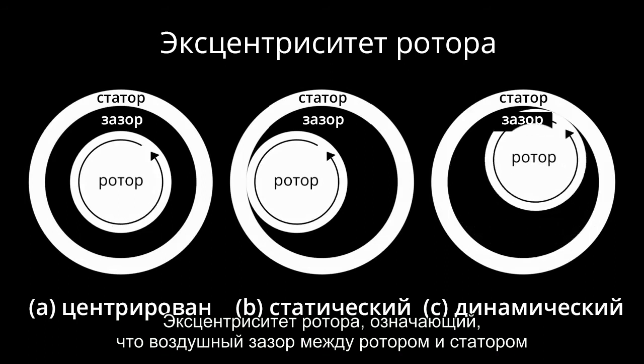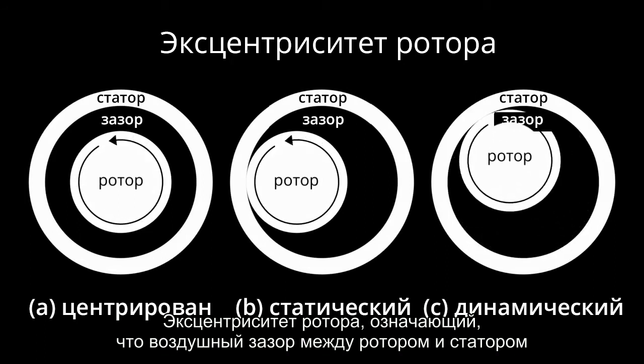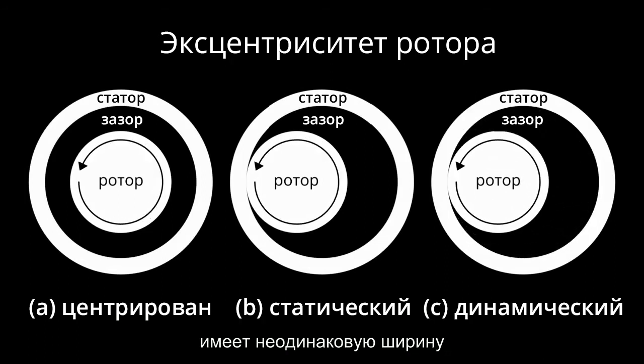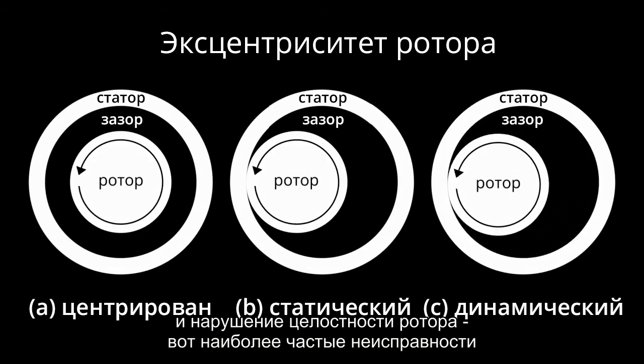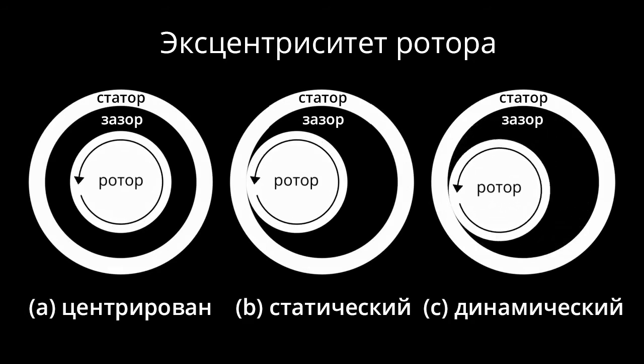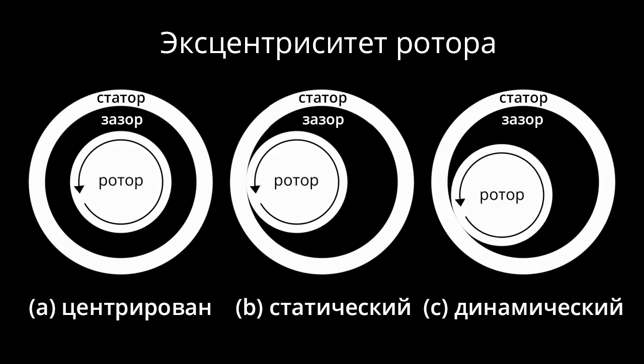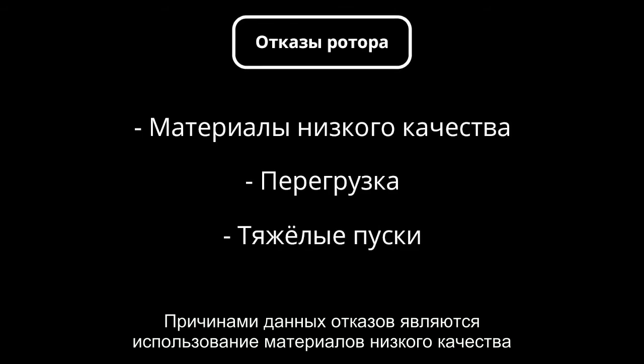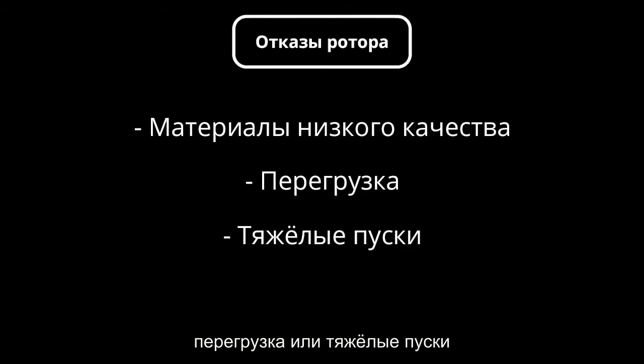Rotor eccentricity, meaning the unevenness of the air gap between the rotor and the stator, and rotor bar interruption are the most common faults. The cause of these faults can be the use of poor quality materials, overloading or heavy starts.